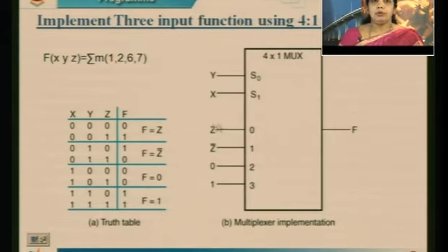So my input to the mux will be in terms of this function. 0 1 is represented as one variable, and that variable is nothing but Z, which I have taken here. So it is Z. If I take it as 1 and 0, the function will be Z bar. If it is 0 0, it is logic 0. If it is 1 1, it is logic 1. So finally these 4 elements are connected as the inputs to the multiplexer.